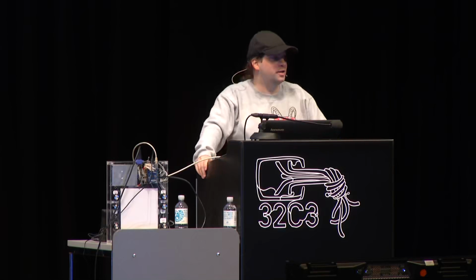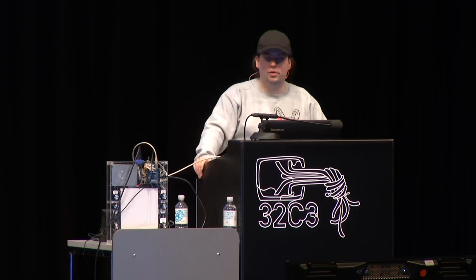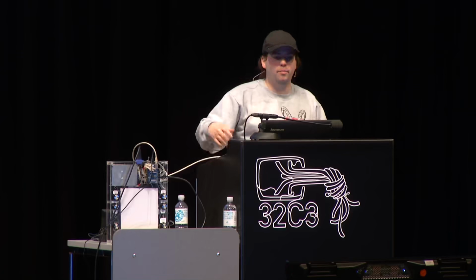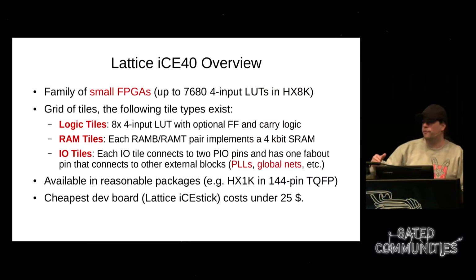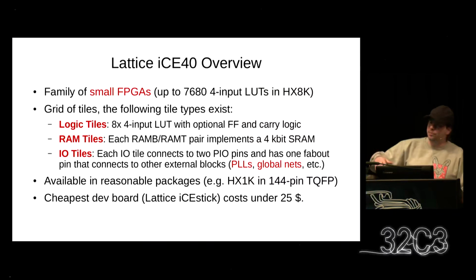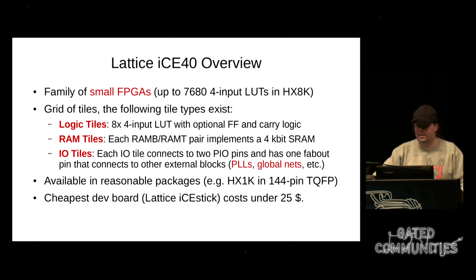There are logic tiles, and those logic tiles have 8 lookup tables, and for each of those lookup tables, an optional flip-flop and a carry chain logic that you can use optionally. There are also RAM tiles for block memory. They always come in pairs. There's always a RAM bottom tile and a RAM top tile, and the bottom tile and the top tile together form a 4 kilobyte SRAM.